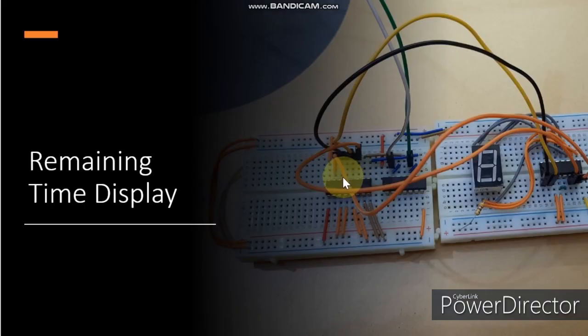To count the numbers, it outputs 0. Through a NOT gate, the enable input T pin was connected to the green LED of the first street. The load pin is connected to the 4017 Johnson counter's first output. As a result, whenever the Johnson counter's first output is high, the down counter resets the value to 7, which is the default value. The enable T pin stops the counter whenever the first street LED turns green.